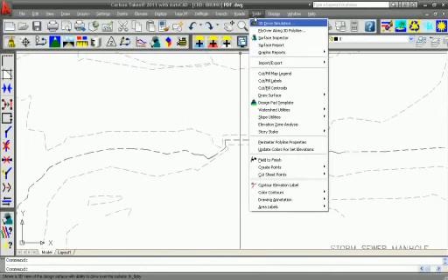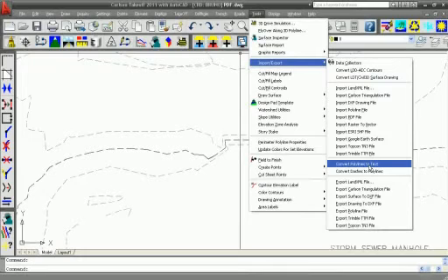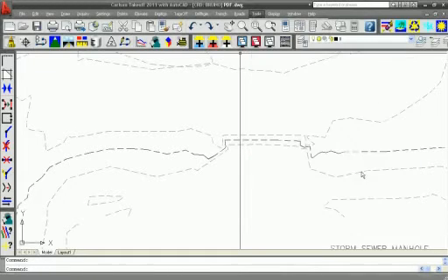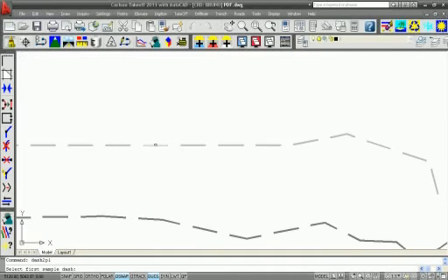But the new routine is under Import Export, and I'm going to say convert polylines to text. Or no, I'm not. I'm going to say convert dashes to polylines. That one's next. Okay, convert dashes to polylines. It asks me for a sample of the dash. So let's zoom in here. Select an adjacent dash line. This is so the program can approximate the gap between the line work, so it knows how to join it. And then it says what to process, and I'll type in all, enter.